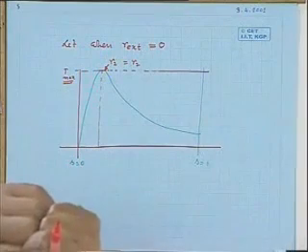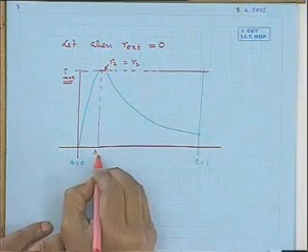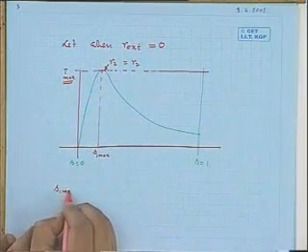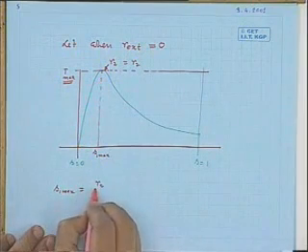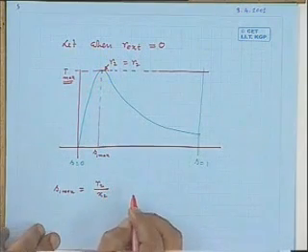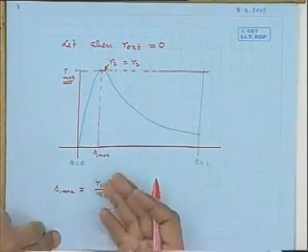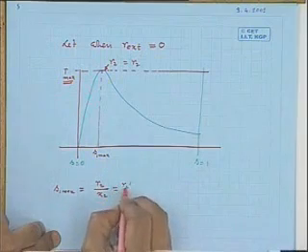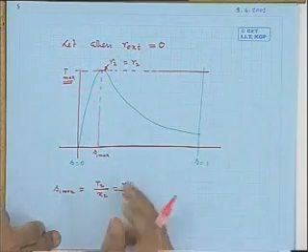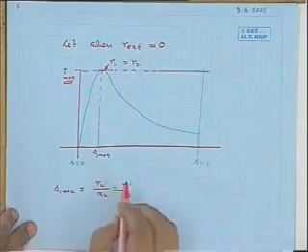Now, does the slip at which maximum torque occurs change? Yes, that will change. Initially, let me write, it was S1 max at which T max occurs. So what was S1 max? It was equal to R2 by X2. This value is the same as R2 dashed by X2 dashed because the turns ratio squared will cancel out, since you are taking ratios. Are you getting it?